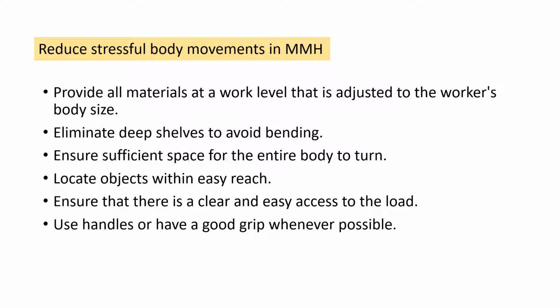Again, I'm emphasizing workplace design, how they design the distance of materials based on the person's anthropometric measurements, how the shelves have been designed, whether there is sufficient space for the body to turn, whether the objects are located within easy reach, whether there is a clear access to the load, or the person needs to have awkward postures to reach the load or the object.